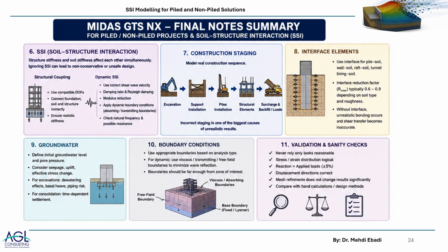Make sure that in your staging sequences, you are not either oversimplifying the project, or considering too many details. Obviously, adding too many details will not in most cases cause technical problems. It will cost you time and energy. But jumping from a stage 1 to a stage 10 will reduce your accuracy in terms of modeling, for example, for an excavation and a staged excavation.